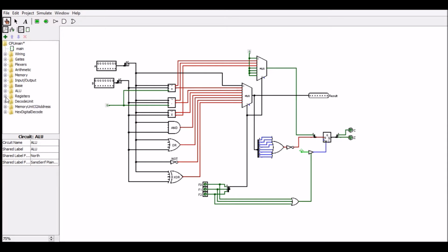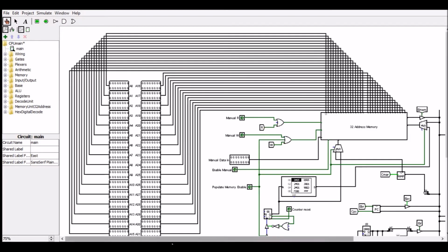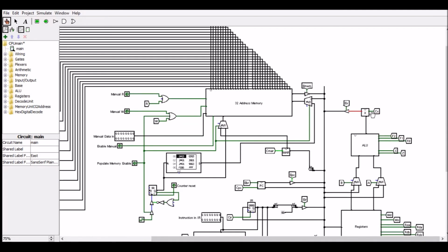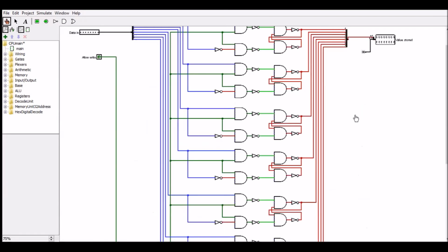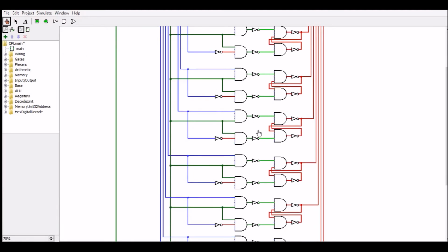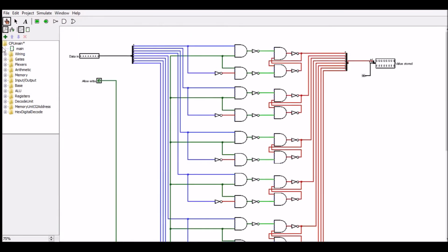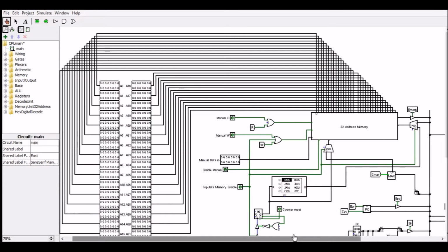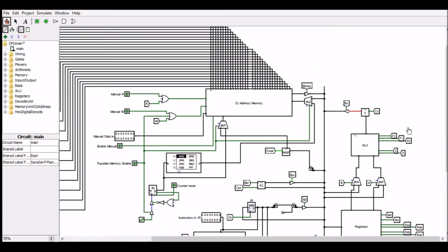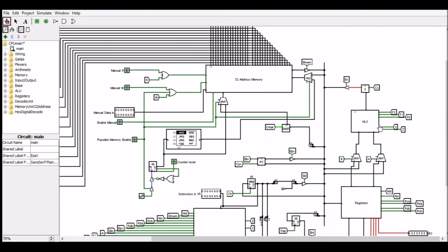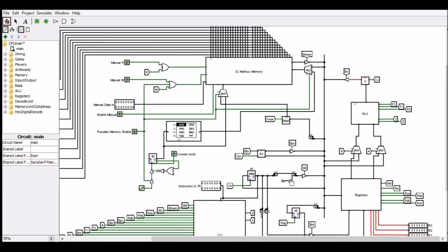So that's the ALU. Something to note is this register X here, which is just a simple 8-bit register, so that you can store intermediate values after an operation has been performed. Generally, if a literal value or a value in a memory address is being used, it will travel along the bus and into the ALU through these multiplexers.